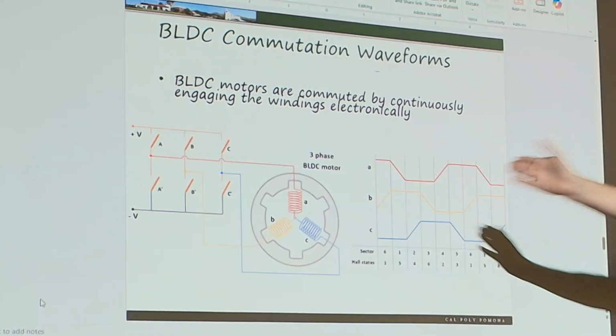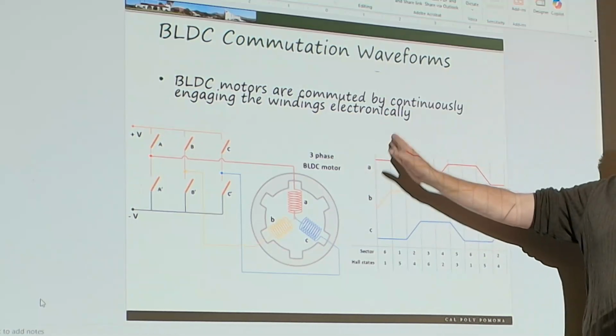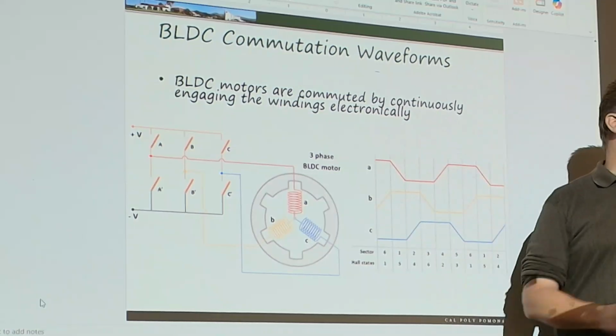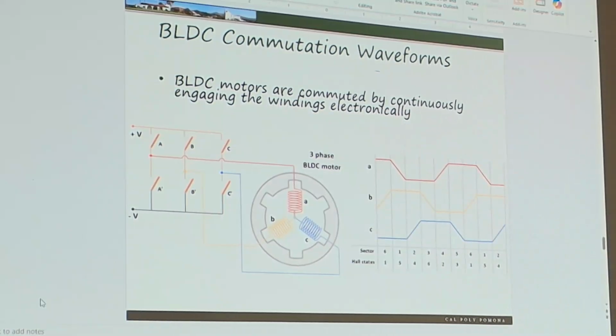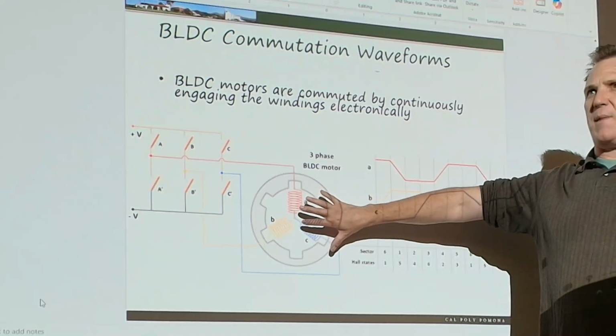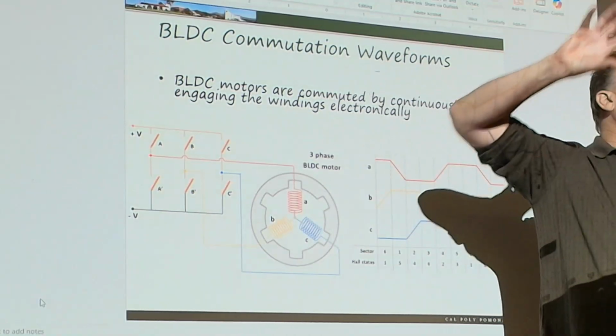So you know exactly where you're at, because when you start, you don't know that starting state. You just say, okay, I don't know what's going on. So in Brex, when we first started doing this a year ago, we were doing our own custom BLDC driver in software. And when you have a really simple motor or a very lightweight motor with not a lot of mass, it just kind of moves to where it needs to go.